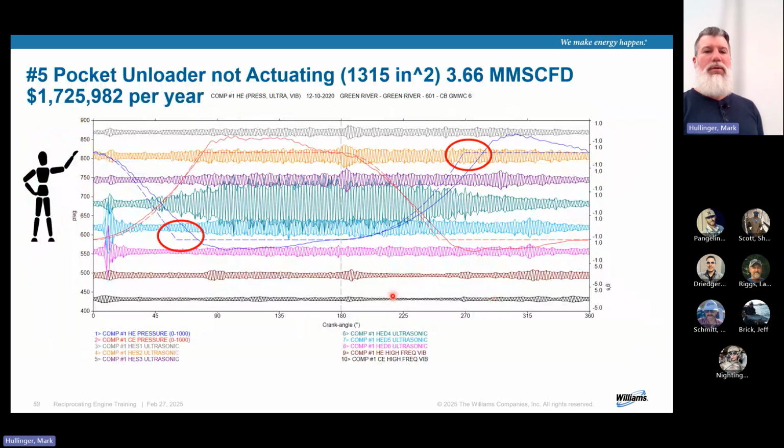Okay. So immediately I see a difference right here. I could say, oh, well, that's probably that valve, but is that valve really causing that? So in the software, I move that load step to another load step lesser. So maybe from 9 to 8 or something like that. I guess in this case, it's 6 to 5. And magically that line lines right up right there.